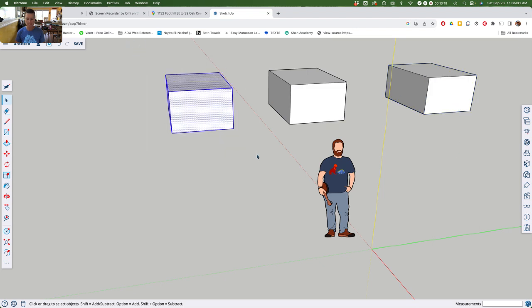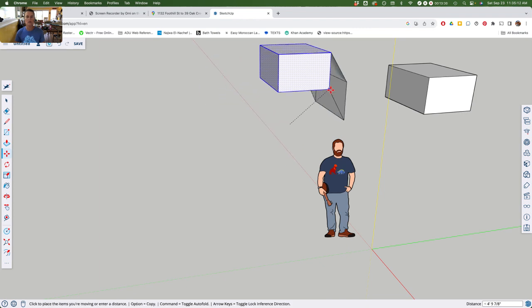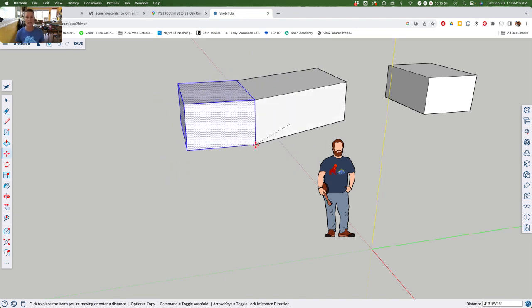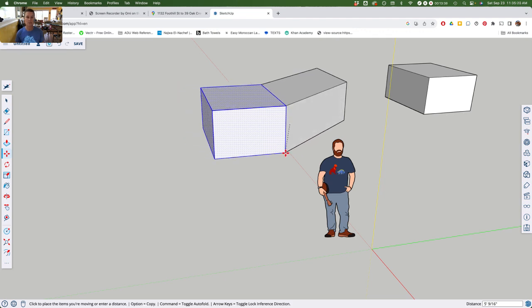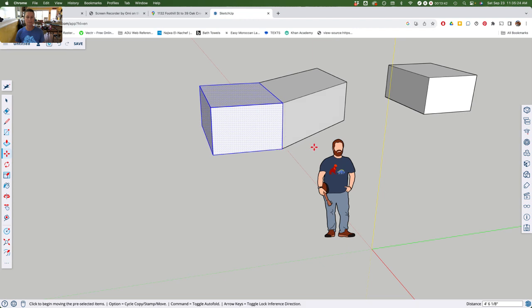So now let's say I want to put one box next to the other box. Okay? But I decide, oh shoot, I actually don't like that. Uh-oh. Now I can't move them, because like I said before, you can only ever have one face or one edge between two objects. So that's not what I want to do. So I can select this and delete this.